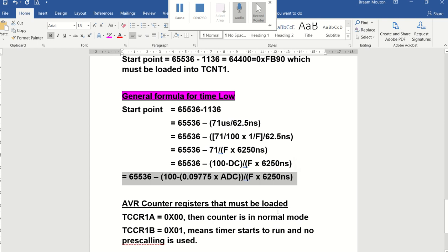And in this specific case, again, the ADC value is received from the output of the ADC, or the input voltage that is changing to the ADC, but also f. You can now change f inside your program. You can actually, at the top of your program, as one of the values that you define, say what f should be.